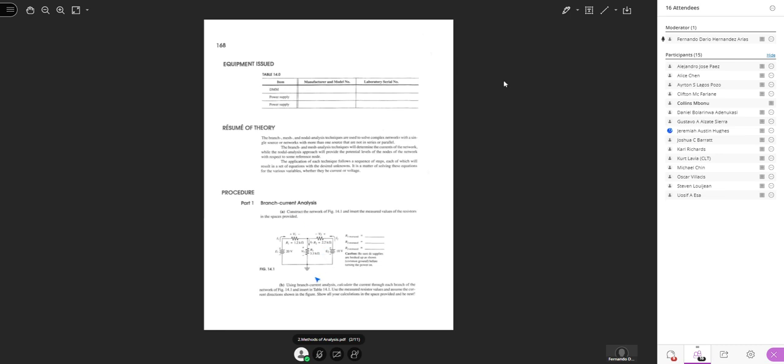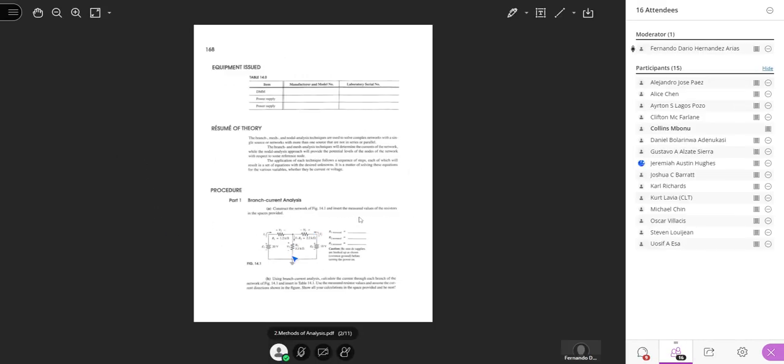Now you have to build your second equation. Let's say you start here, and you go around this loop, adding all the voltages. It's going to be plus 10 volts because you go from minus to plus, right? So plus 10 volts minus V2 minus V3.